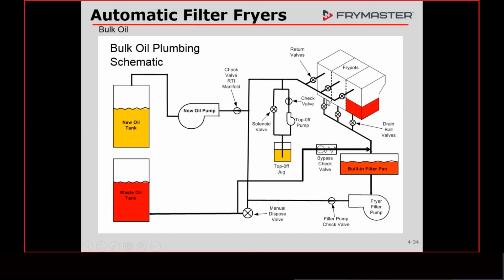If you go out to work on a top off system, do not start looking at the biggest issues. Look at the simplest ones first, and I bet you're going to find your problem before you actually have to start changing any parts. But anyway, this plumbing schematic is in the tech reference manual as well.